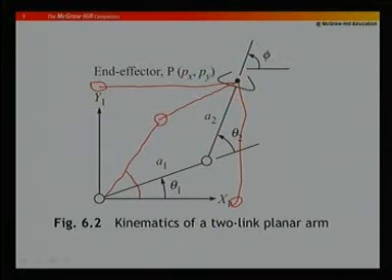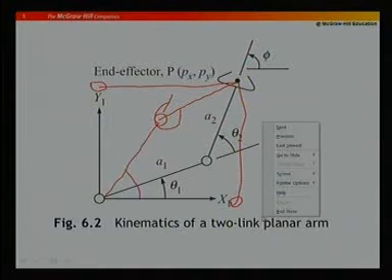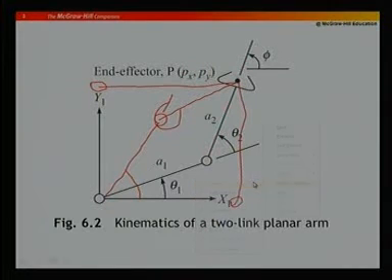this is 1 theta 1, and if I draw a line here, I can get another theta 2. So, notice for 1 Px and Py, I can get 2 theta 1 theta 2, but for given 1 theta 1 theta 2, I can get only 1 Px Py. What does it mean? For the direct problem, when I give theta 1 and theta 2, it has a unique solution, that means Px and Py. But for inverse kinematics, where Px, Py is given, this has multiple solutions.